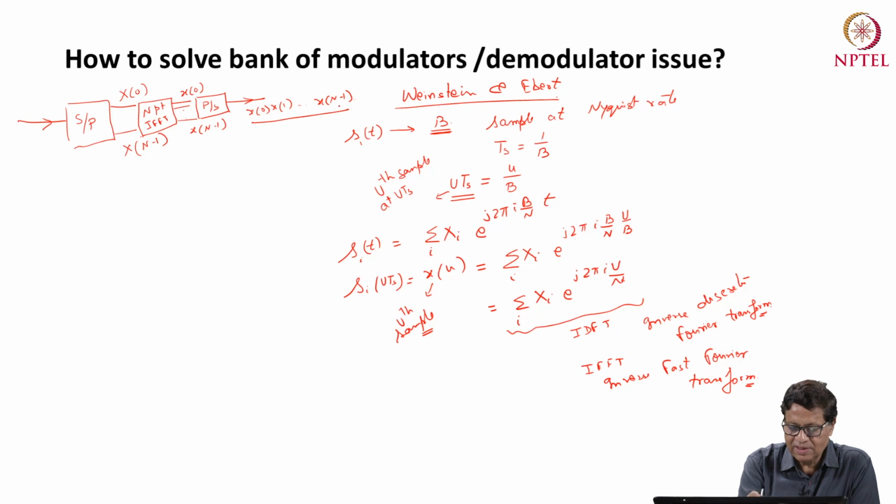So this whole thing is an OFDM symbol. Actually the CP, that cyclic prefix, is also added. Right now I'm not adding it, but first I have to explain why CP is added. Then actually the whole signal, when you have the cyclic prefix and this whole symbol, that becomes an OFDM symbol.